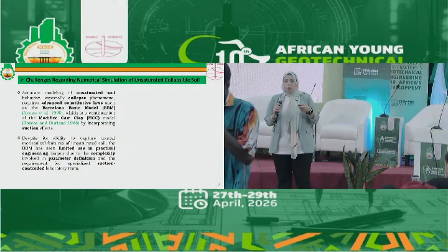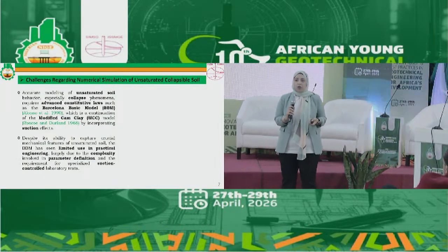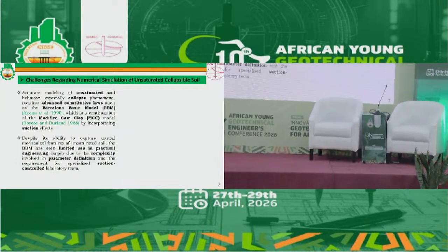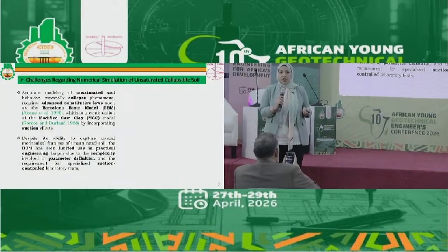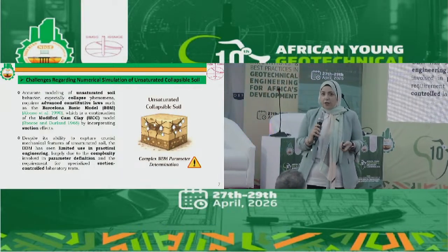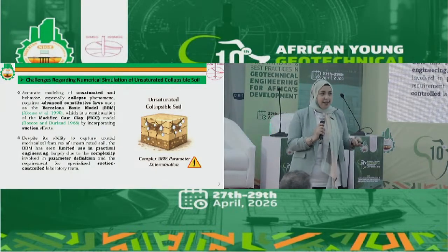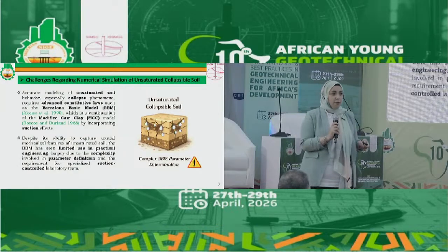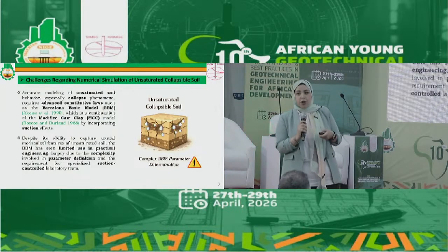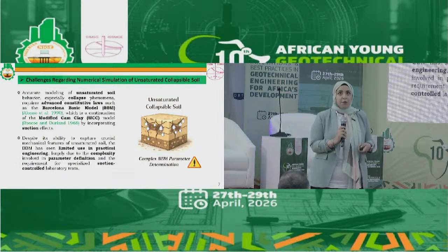The problem with numerical modeling of unsaturated soil is you have to choose the accurate constitutive model. And I chose the Barcelona Basic Model, which is generally a continuation of the Modified Cam-Clay model, but it incorporates suction effects. And this is the problem: it's very difficult to determine the parameters of the Barcelona Basic Model because you need very sophisticated tests, especially suction controlled, and you need suction measurements. And once you do those expensive tests, either triaxial, you have to determine the data and you have to determine the parameters itself, which is a very difficult and tedious procedure.